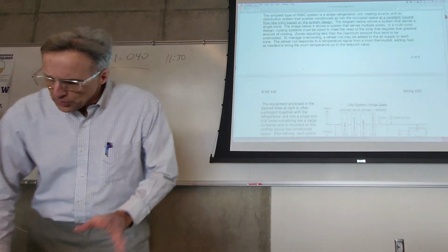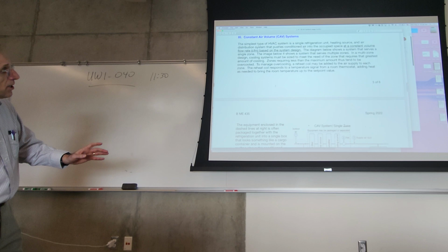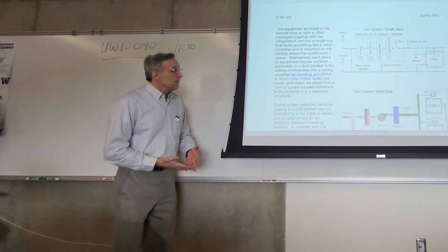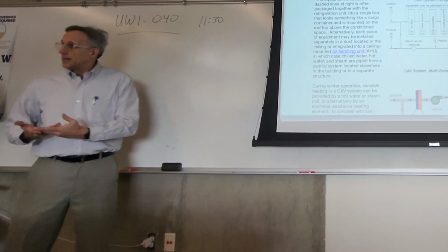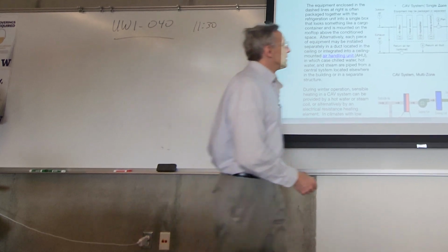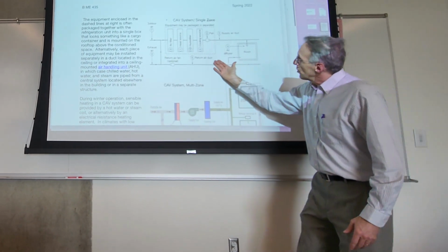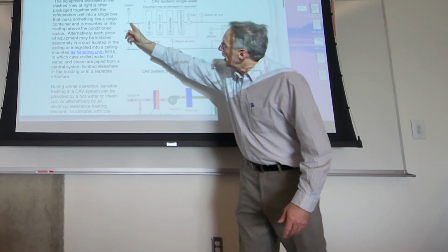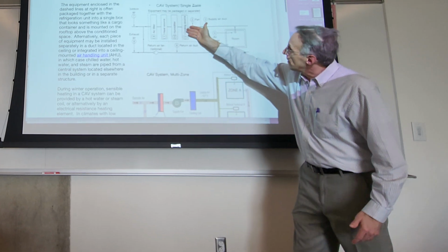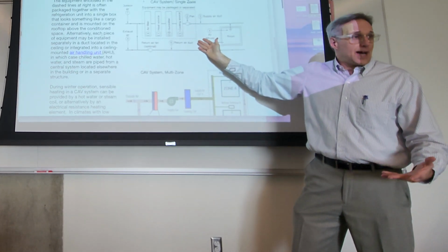And so I'll talk a little bit about the two main types of air systems: the constant air volume system, and that's really what we've been looking at most of the time. This is the bread and butter HVAC system, the most common, the traditional, where you've got a space, you draw the return air out, mix in a little outdoor air, filter it, heat, humidify, cool, and dump it back in the room. And we've already analyzed that, right? We know how to do that.